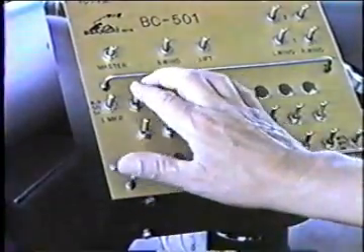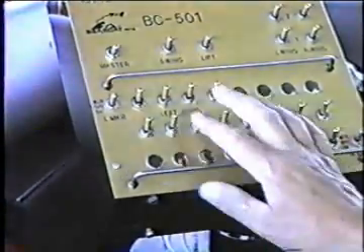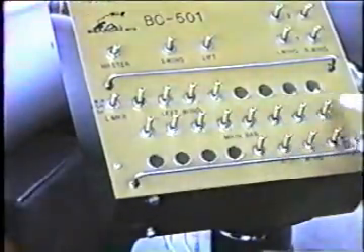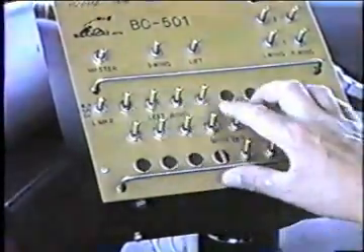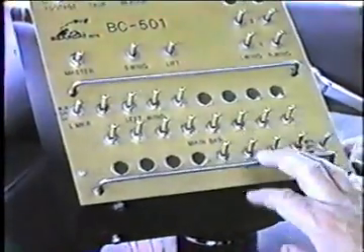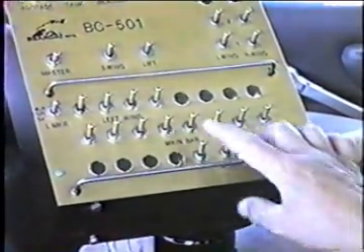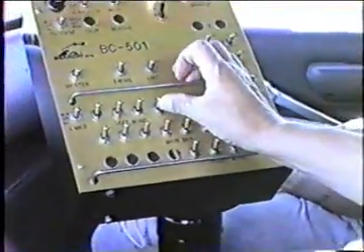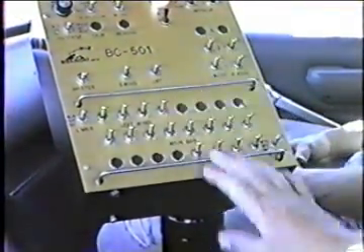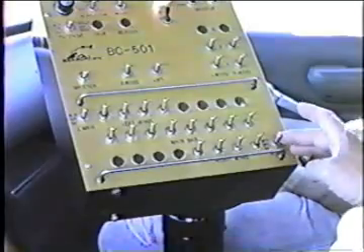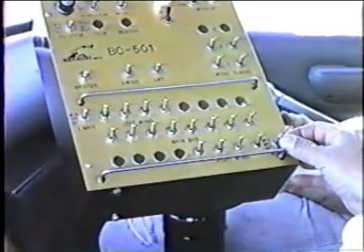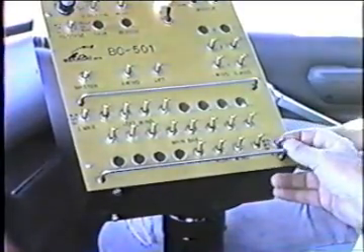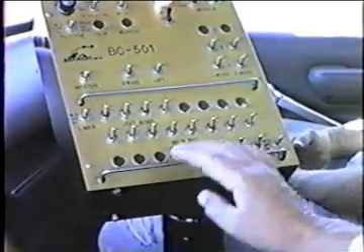Left wing going across, this particular truck is in 1 foot sections, 4 feet on the left wing. Then the main bar is 8 switches long, or 8 feet long, and the right wing below, 4 switches for the 4 foot right wing. Everything here up is on, down is off. Right hand marker, same as the left hand marker. Master position, off position, on to marker line position. Center off.